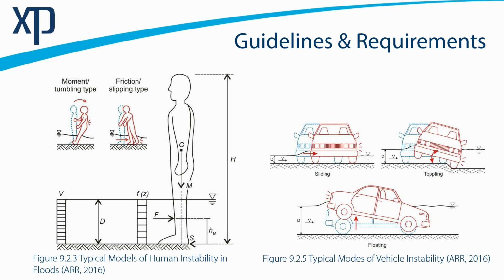And so if you have a 3 metre per second flow, the maximum depth should only be 0.1 of a metre on a road. And so that DV combination becomes very important to protect vehicles and humans. So have a look at that reference guideline later to track some of those more detailed numbers down.